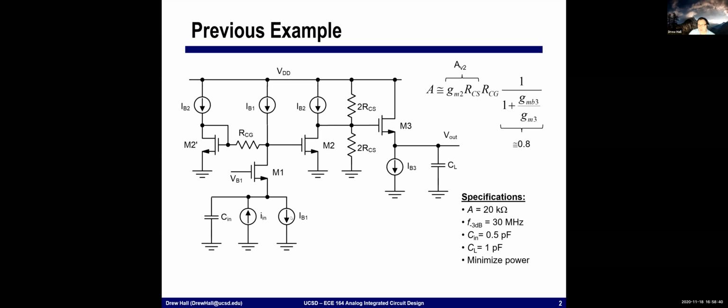And so I would encourage you in your design as well, your first pass simulation should not be the first figure of the project with every single transistor. We should focus on things like the signal path. So you should do that common source amplifier. You should simulate the folded cascode. Only then would I start to go back in and dial in all of the biasing.